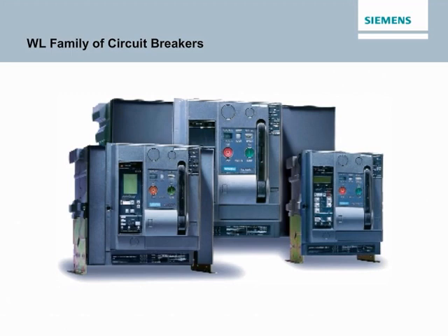The circuit breakers discussed thus far in this course are molded case circuit breakers that conform to the UL 489 specification. This specification also covers a category of molded case circuit breaker commonly referred to as an insulated case circuit breaker, an ICCB. ICCBs are generally used in switchboards and may be fixed mounted or drawer-out mounted.